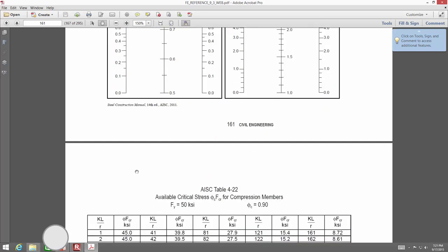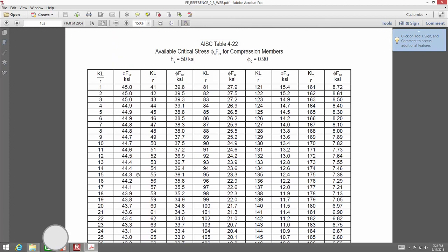All right. Now, this one is definitely one that I would bookmark or indicate in your head. If you all remember in steel design, there were a few different ways that you could calculate the capacity of a column. Now, you could just brute force it and use the equations, but one of them is that you could use the slenderness and, based off the slenderness, get a factored stress straight from this table.